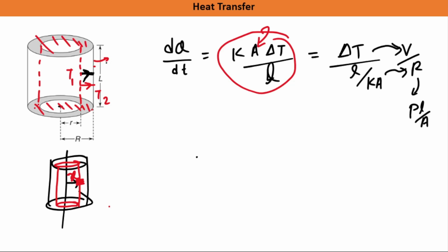So similar thing. If we are able to calculate the resistance of this cylindrical conductor for radial flow of heat current, we can get the answer for heat current value. ठीक है, so चलो एक काम करते हैं. Let us talk about the solid cylinder first, and when heat current has reached this point, how much resistance will this red portion of cylinder of thickness dr offer to the heat current.